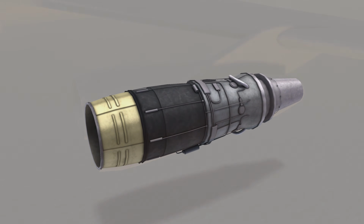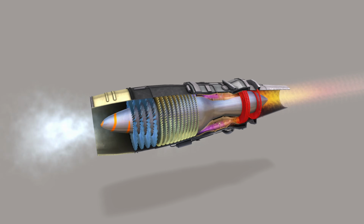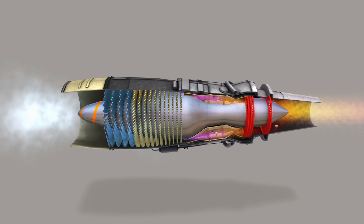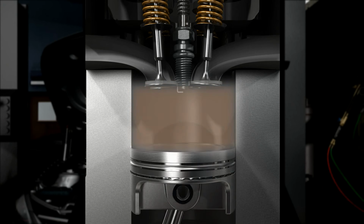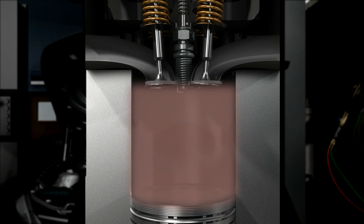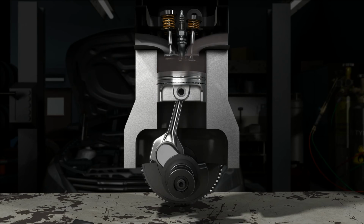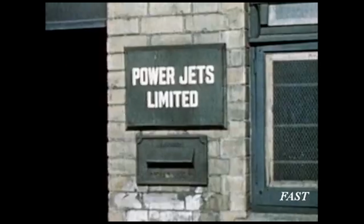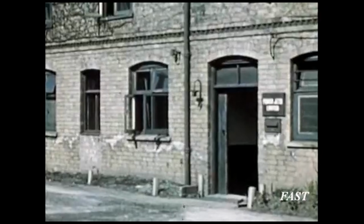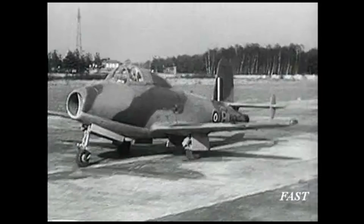The jet engine is the technology that underpins the majority of modern aircraft propulsion systems. A jet engine has a continuous throughput of air and a constantly burning flame. This is unlike a piston engine used in a car, where combustion only occurs during one of the 4 cycle strokes. The earliest jet engine was designed by the legendary Frank Whittle in 1932 and was eventually produced by Frank Whittle's Power Jets Company in 1941 as the W1, and it was used in the Gloster E.28 aircraft.